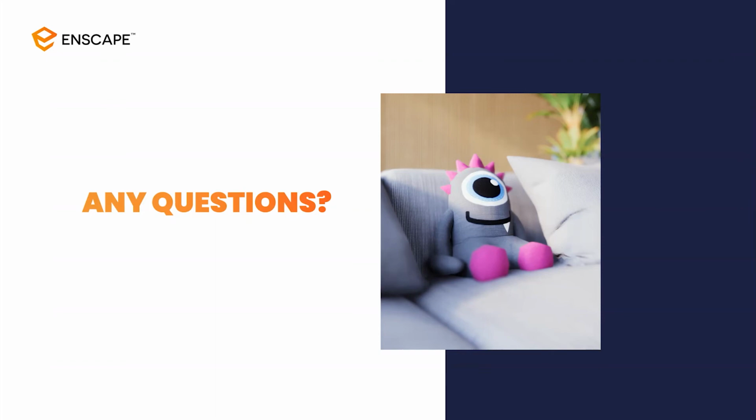Enscape is a GPU rendering engine, so if you can run Revit just fine, you can run Enscape, but you just need a dedicated graphics card. If you're doing virtual reality or plan on doing a lot heavier models, I'd recommend bumping up to at least an 8 gig video card. My machine currently is running an 8 gig RTX 2070 Super. So again, hopefully that helps answer that question.